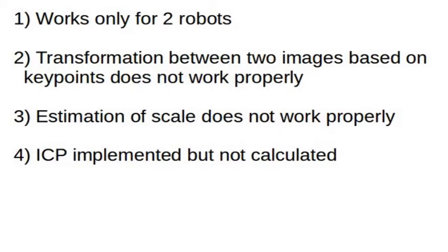Every time a place recognition is detected between 2 different robots, SIFT key feature points are detected and matched. From the matched feature points and corresponding inverse depth values, the 3D world points are calculated. Note here that in general, the locations and hence the related pixels of the key points are totally independent from the pixels for which a depth value resulting from LSD-SLAM is available.